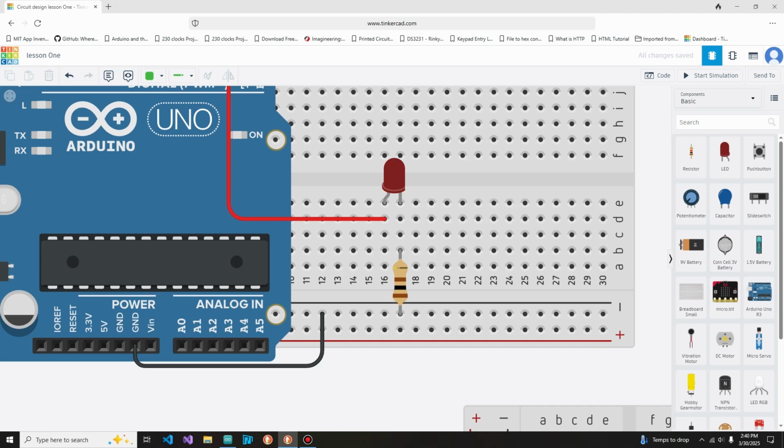Silver is 10%. So the different colors, and that's not hugely important, especially for general projects. If you want to get into uber specific stuff that's super sensitive, then you want stuff that's very on point. And so that band will probably turn red. But for the most part, and a lot of the projects we're doing now, you're not ever going to have to worry about that. And most general use resistors are going to have a gold band anyways.